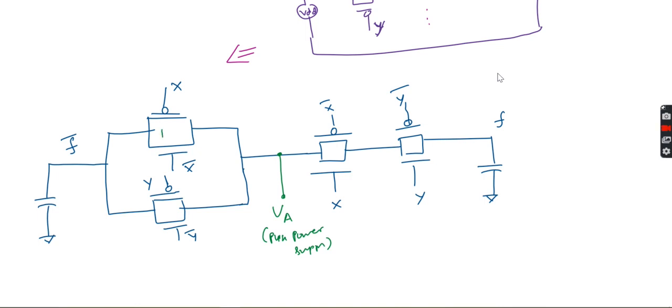Now this is TG1, this is TG2, this is TG3, then TG4. Note that the number of transistors required for realization of the adiabatic circuit will be larger than the static CMOS realization of the same function. Like this you need to implement not only for the NAND gate, but also for the OR gate and even for complex logic. These realizations we will see in further classes.